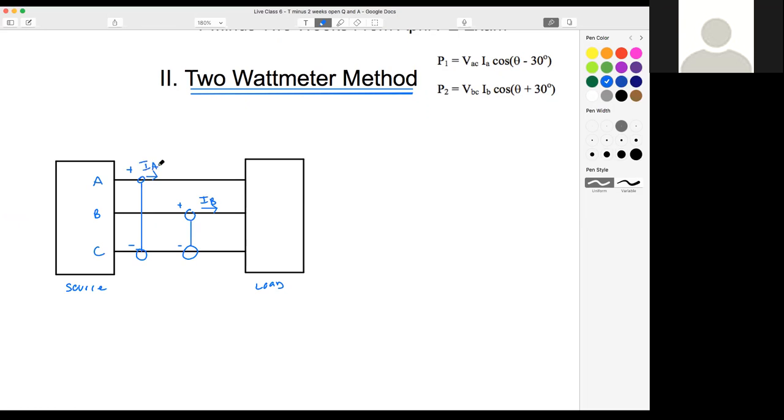So really important. Essentially, it doesn't matter. We can arrange this in several different configurations, but the important part is that our watt meters have the same phase as your negative voltage reference. Does everyone see that? In this case, it's C phase. That has to be the negative reference. We can't do a plus and a minus up here. We're going to get the wrong answers.